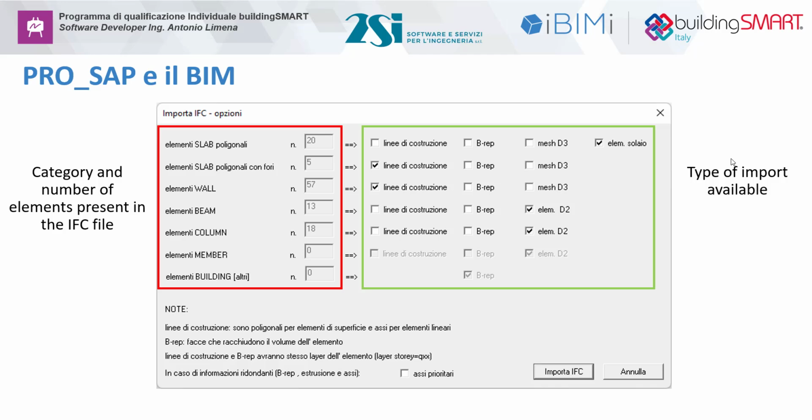Why am I saying correct the geometry? Because as I already showed you, when you import the file, you want to obtain a model ready for the analysis, but all the elements will be separated from the others and not connected with nodes. Except, of course, if you import an IFC file generated by another FEM software.